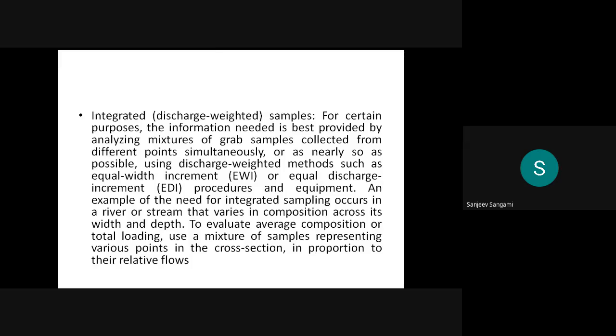An example of the need for an integrated sample occurs in a river or a stream that varies in composition across its width and depth. To evaluate the average composition or the loading, use a mixture of samples representing various points in a cross section in proportion to their relative flows. So integrated sampling means it is discharge weighted, as discussed in the paragraph.